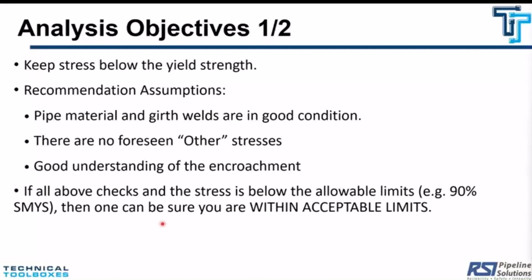So the CEPA model, the focus of today's seminar, is just surface loading from vehicles. If a vehicle crosses a pipeline, that's called surface loading stress analysis. That's the type of analysis we perform to make sure that the pipeline is safe, right? And the objective of the analysis is to calculate the stresses in the pipe, longitudinal stress, circumferential stress, whatever, and to show that those stresses are acceptable, right?